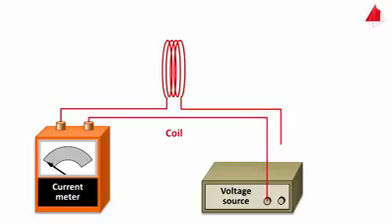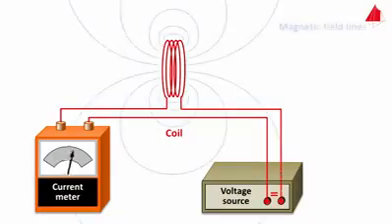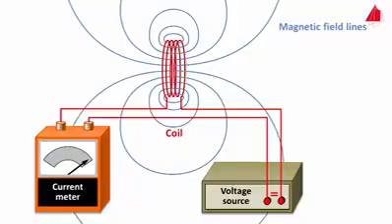It is based on electromagnetic induction. The animation shows a coil, which can be connected via an electric current meter to a voltage source. After applying a direct voltage to the coil, the electric current first increases fairly quickly, then more slowly, according to the inductance of the coil. Eventually it reaches a level resulting only from the ohmic resistance of the coil.